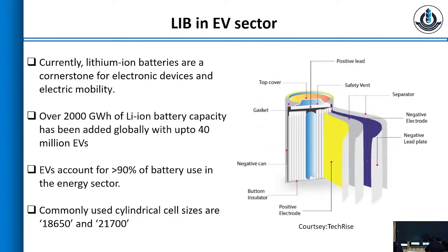Okay, so if you look at the structure of a cylindrical cell, you see layers of cathode, anode, separator, along with the electrolyte in between. So you have alternating arrays of cathode and anode, with layers of electrolyte and a separator in between. They are like wafers which are rolled in the cylindrical format. This is the typical configuration of the cells that we use. And then we stack these cells in cylindrical arrays, either in hexagonal form or cylindrical form, so that you get a battery pack.